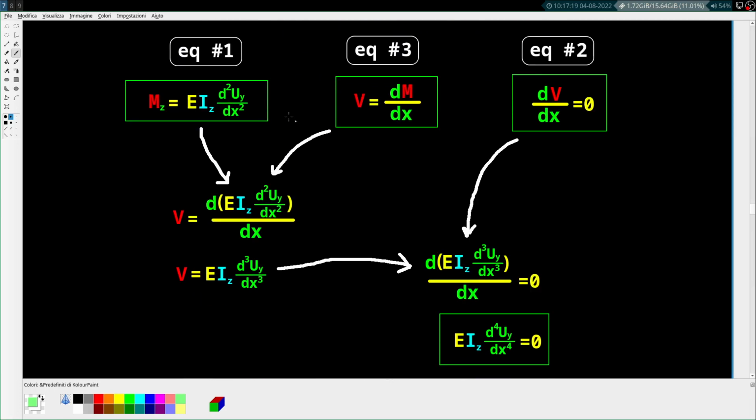And now we'll put those equations together. So equation 1, substitute in Mz for M, take the derivative. This is what pops out. We're just taking another derivative of this. And the signs, don't worry about the signs. The signs I'll explain later. We'll get into what all that means later in a very clear way. And then we plug this equation here into equation 2, pull that out. That's EI, the fourth derivative, equals 0.